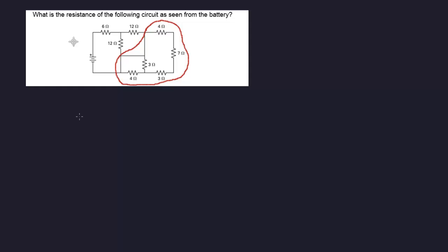It's the same thing as if we had a capacitor or an inductor. I think I've talked about it in earlier videos: when you have a capacitor in a DC circuit, you have an open circuit. There's no current that would flow through that capacitor. And if you have an inductor in a DC circuit, again I'm talking about DC circuits here, then you would have a short circuit for that inductor. So if we had an inductor here and an inductor here, we would have the same circuit. We would short it out just like here, and take this whole part out of the circuit.